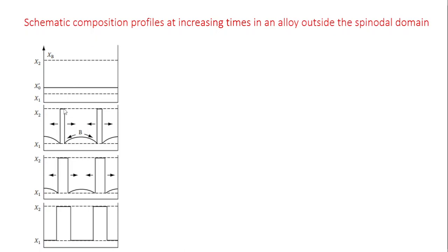So here what you see is x2 nucleating from x0, from a phase which has a composition x0 prime, and x2 is much richer in beta than the average composition. For this to happen, the B atoms have to diffuse from outside the growing phase particle to the phase particle.